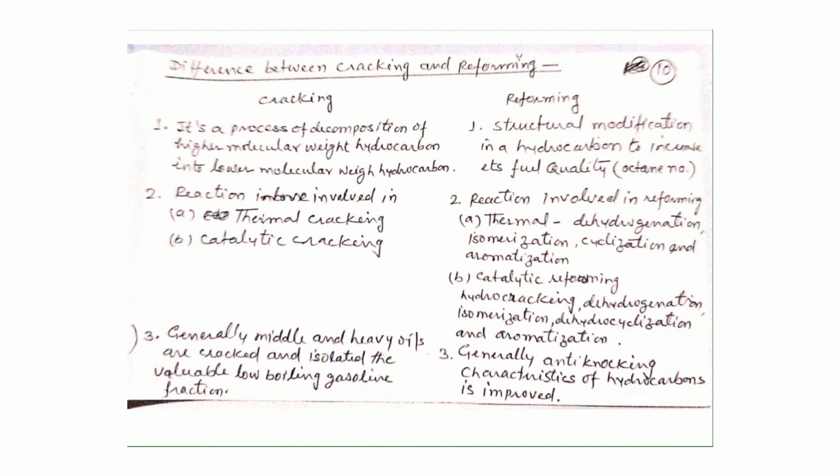The reactions involved in cracking are thermal and catalytic cracking, the two types. The reactions involved in reforming are, in thermal: dehydrogenation, isomerization, cyclization and aromatization; and in catalytic reforming: hydrocracking, dehydrogenation, isomerization, dehydrocyclization and aromatization.